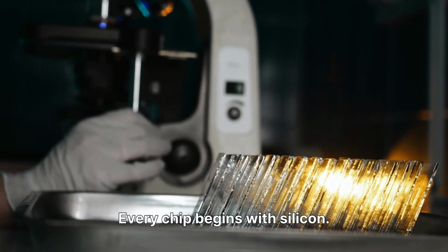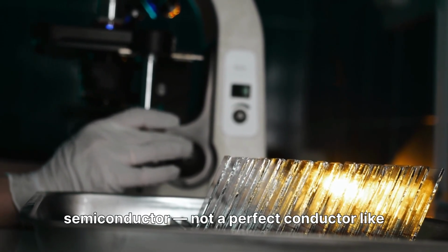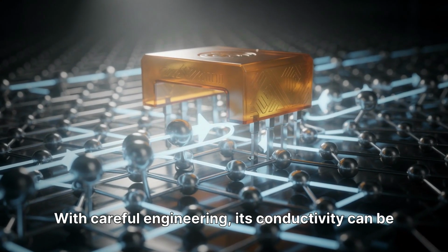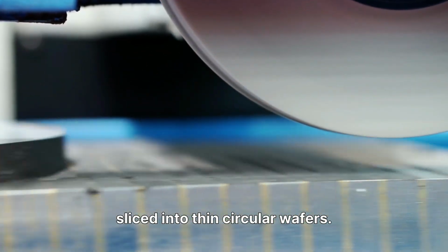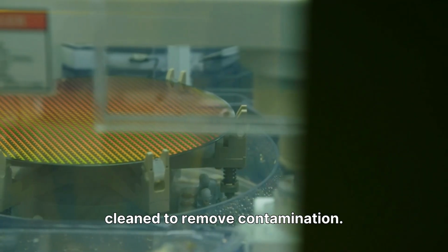Every chip begins with silicon. Silicon is chosen because it is a semiconductor, not a perfect conductor like copper, and not a perfect insulator like glass. It sits in between. With careful engineering, its conductivity can be controlled. The process begins with ultra-pure silicon. It is grown into a single crystal ingot, sliced into thin circular wafers, polished until the surface becomes mirror smooth, and cleaned to remove contamination.